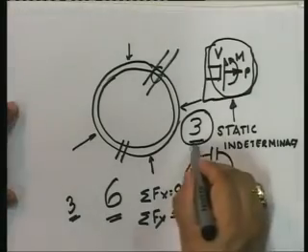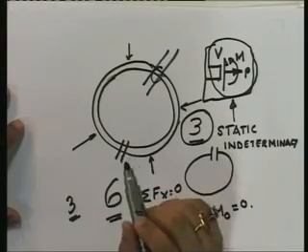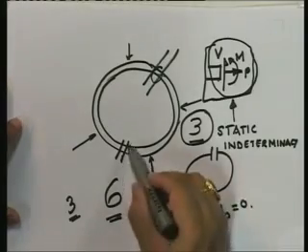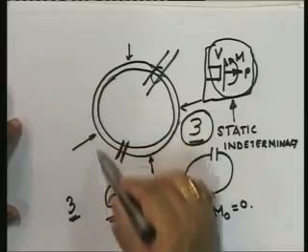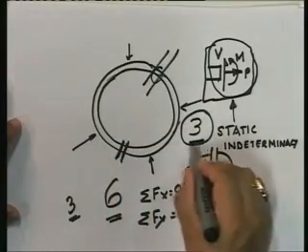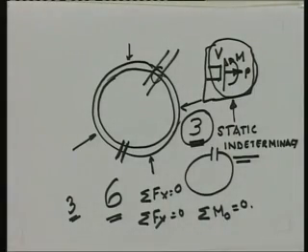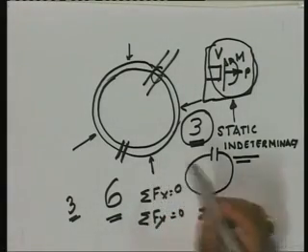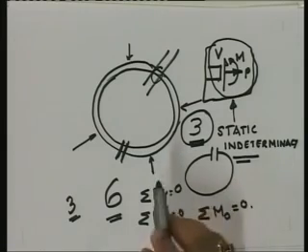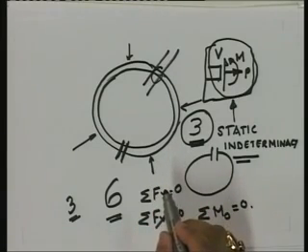So therefore, this is fundamental. Please understand that this is how we generate it. That a ring has 3 degrees of static indeterminacy. This I am going to be using to find out the static indeterminacy of a plane frame structure. So now, remember, how do I create a ring? Can I take a structure and make it into a ring? Well, actually I cannot. So I have to think a little bit and do it.